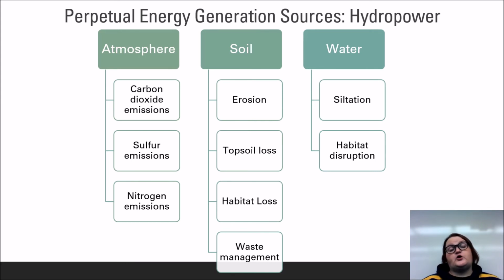Sedimentation happens more quickly in the reservoir area behind the dam. This reduces the volume of the reservoir, leading the water to either spill over its containment and flood the surrounding areas, or to push through the dam itself, potentially corroding components with sediment. Proper management of this process must be maintained, or a dam could suffer catastrophic failure.